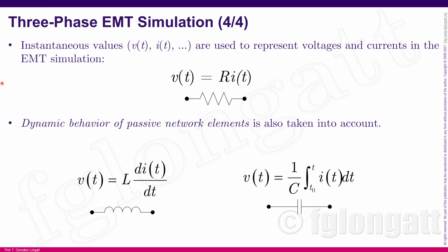And as you must be aware, the inductance and the capacitance in the electrical power system are usually very low. And that is the reason that the dynamics involved in this case are extremely, extremely fast, okay? And it's related to the energy interchange between those inductors and capacitors. And that is the reason for the name electromagnetic transient, okay?